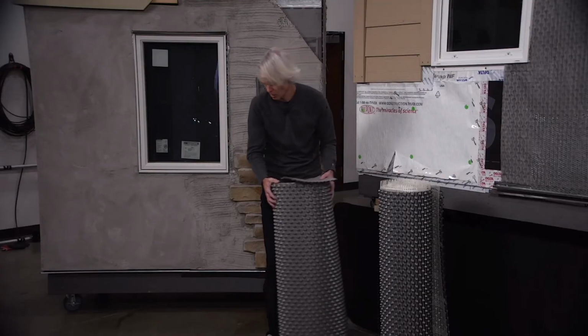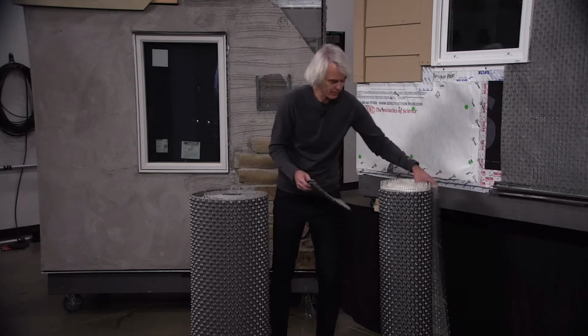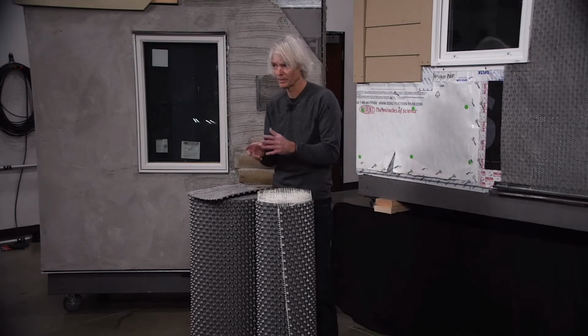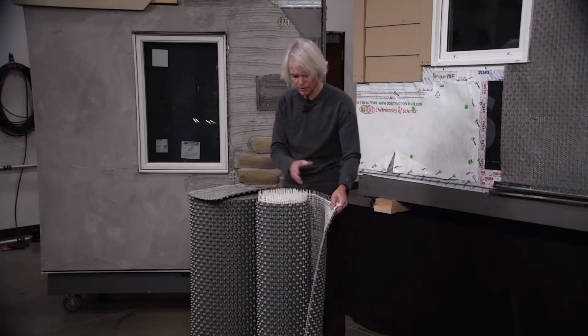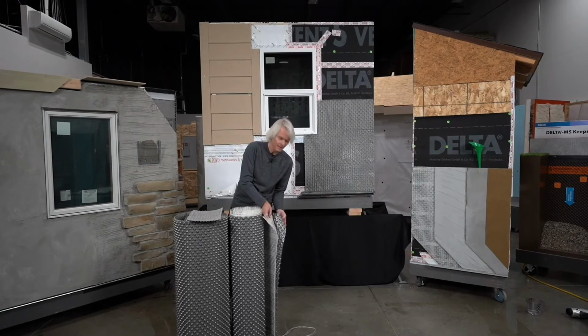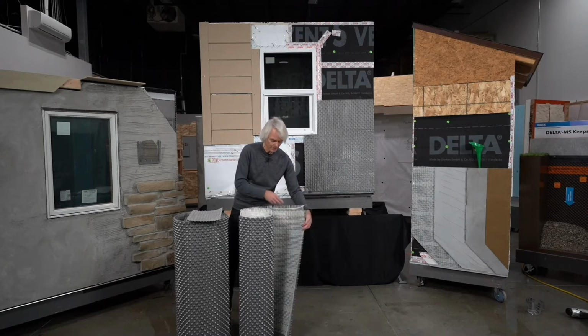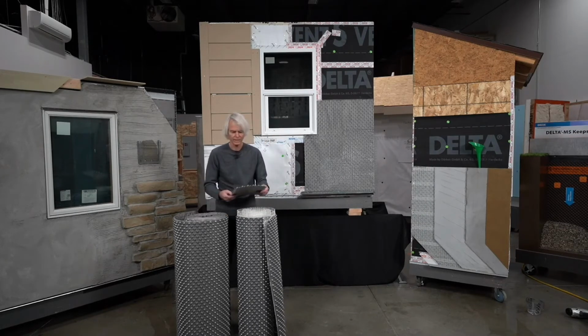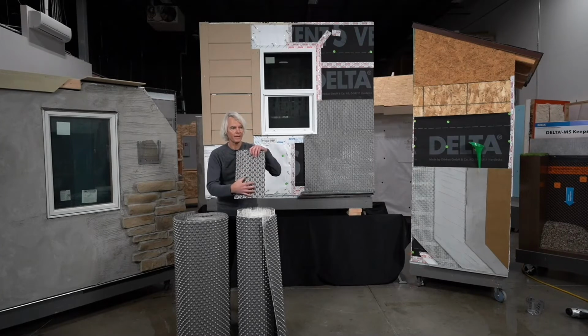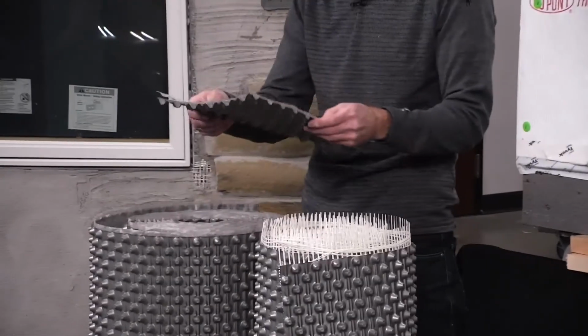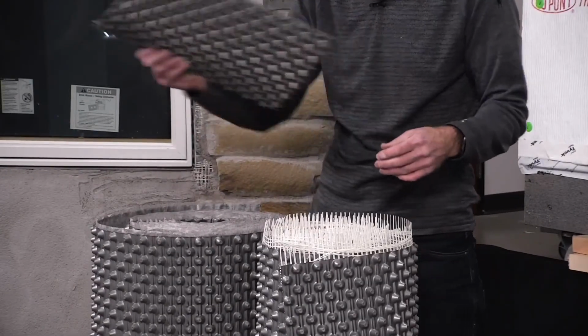So let's just take a moment, while I'm standing in a puddle here that we've created from that rapid drainage, and recap a little bit about some of these rain screen products we've been talking about today. Here's our first product, again, the Delta Dry and Lath product, and we've got this integrated, very unique lath to it. Both of these products I'm holding have slight differences, but the ingredients are really the same. It's really about this sheet that you have on the front. It's high-density polyethylene. It's very crush-proof and very lightweight. It cuts with a standard knife or scissors very quickly, but you can see it's very light.